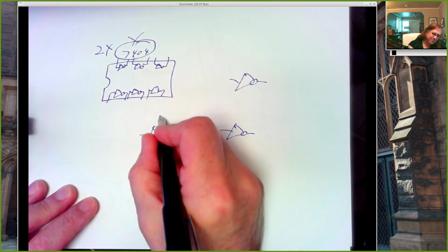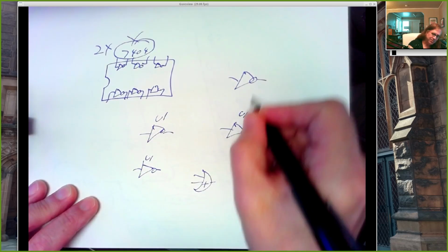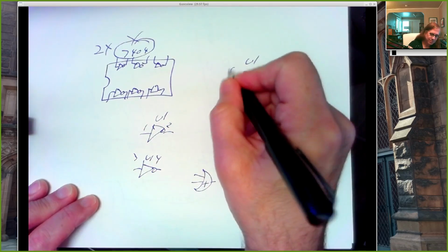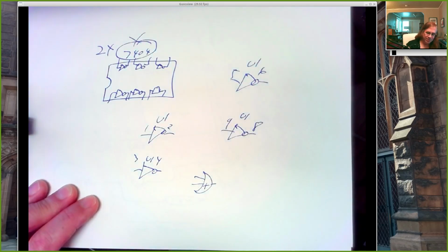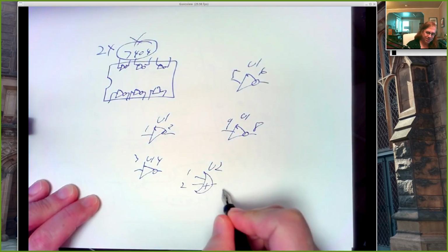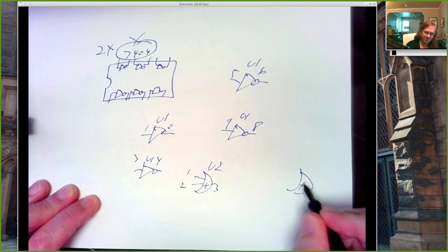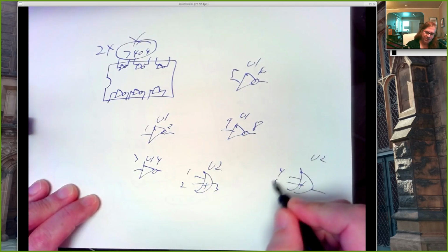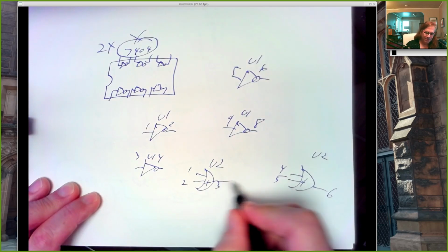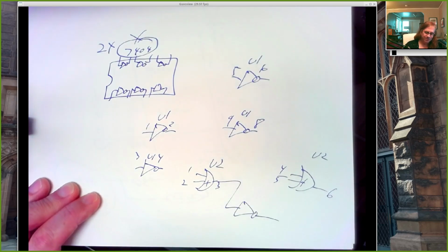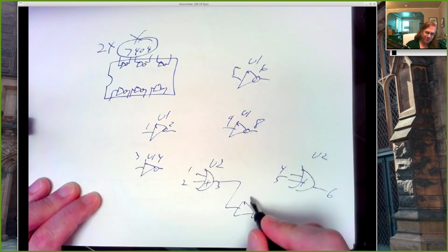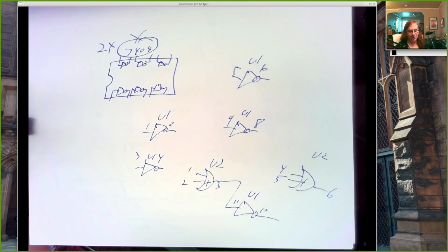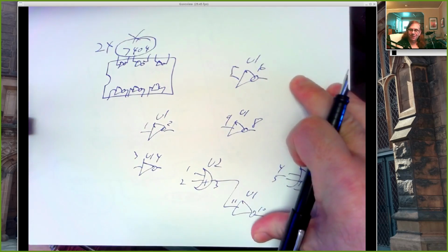Okay, well, this can come from package U1, and you pick some pin numbers. And this is going to have to come from U2, and I'll pick some pin numbers there. And if I've got another OR gate somewhere, well, that can also come from that same chip, U2, and I'll use these pin numbers. And maybe this is going into another inverter. Well, let's see, U1, I've only used 4 of them. I can take my 5th one from here, and so that can go right there, right? And you do this before you ever open Tinkercad.